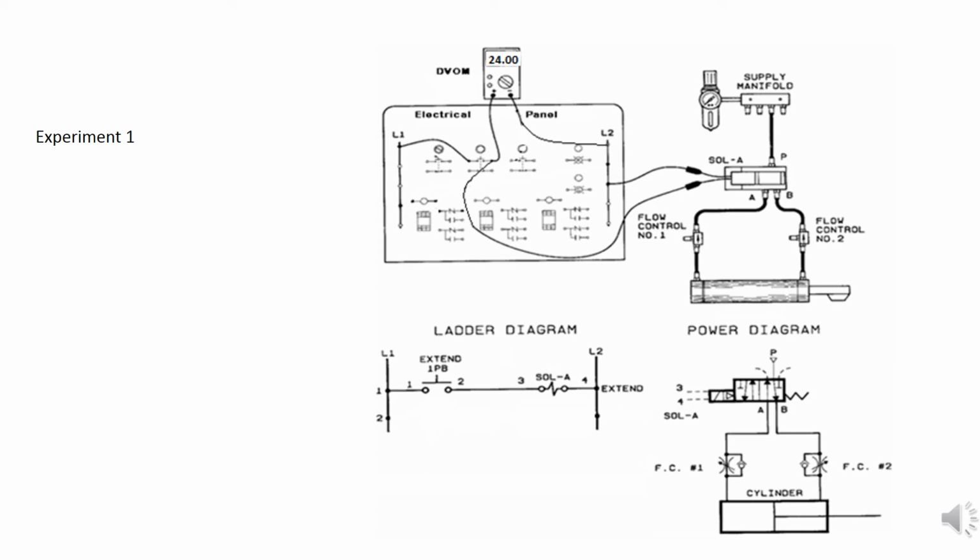So basically you push the button, the cylinder extends, you release the button, power is discontinued, the spring pushes the valve back to the normal position, and the cylinder retracts.